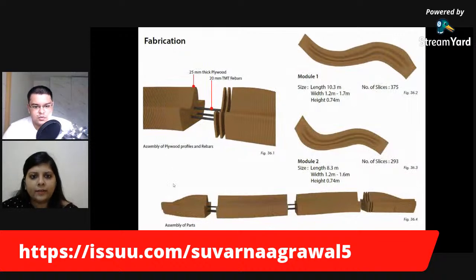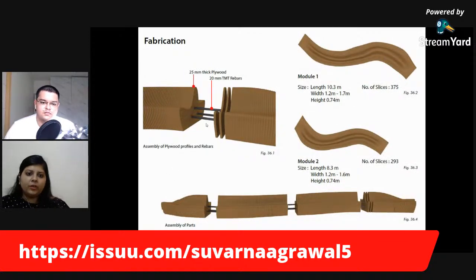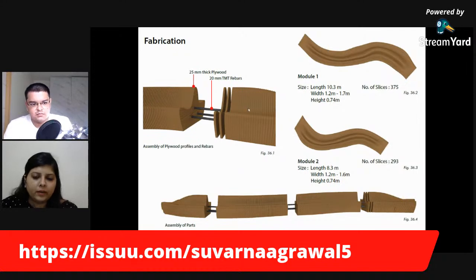So another thing that I was talking about was fabrication. Now that you have designed, how do you fabricate it? This is something that we have been doing since day one. This shows how we need these plywoods and how we need to connect them. How do you keep it stable? And what kind of length you have, how many slices. These are called slices, all these individual members. So this is how the parts would be assembled.